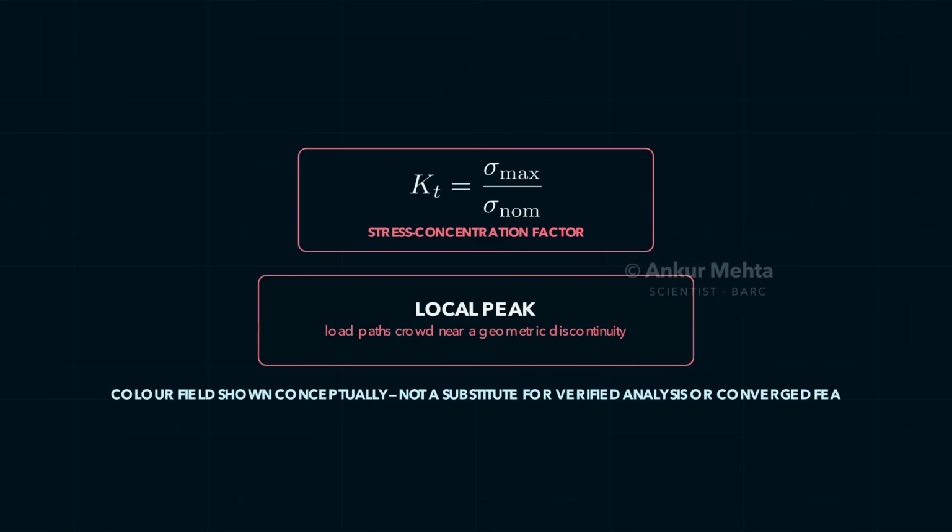This is why a smooth radius is safer than a sharp re-entrant corner, and why failure often begins at a notch. In this lesson, the color field is conceptual. Quantitative design requires a verified analytical solution, experimental measurement, or a properly converged finite element model.